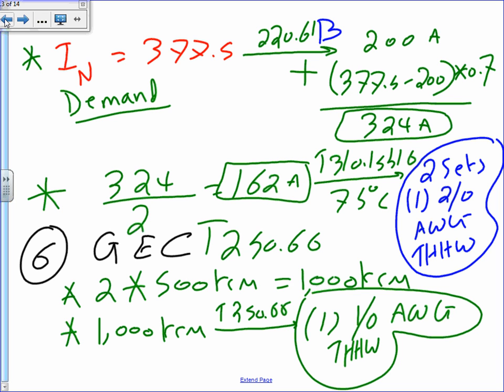Up to 600 to 1,000 is 2/0, yeah. So who gave me the 4/0? This is a 2/0, right? It's over 600 up to 1100, which gives you 2/0. Okay? I'm going to move it away. 2/0.